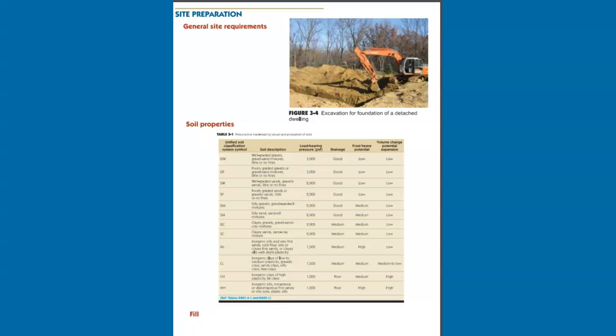In some cases, it may be possible to remove unsuitable shifting or compressible soils from the building site and replace them with approved fill to stabilize the soil below and around foundations. Under these conditions, the IRC permits a prescriptive foundation design without a full geotechnical evaluation. Ref. R 401.4.2, fill.